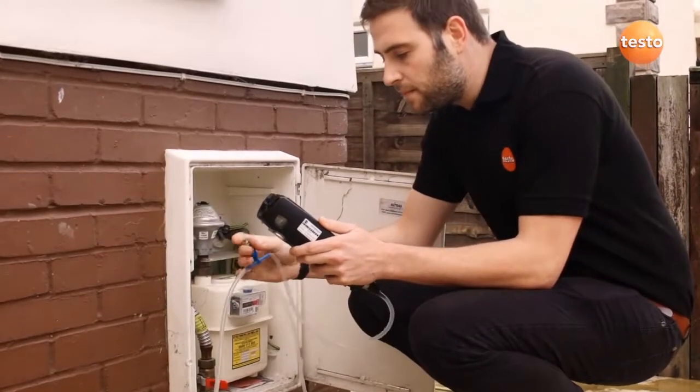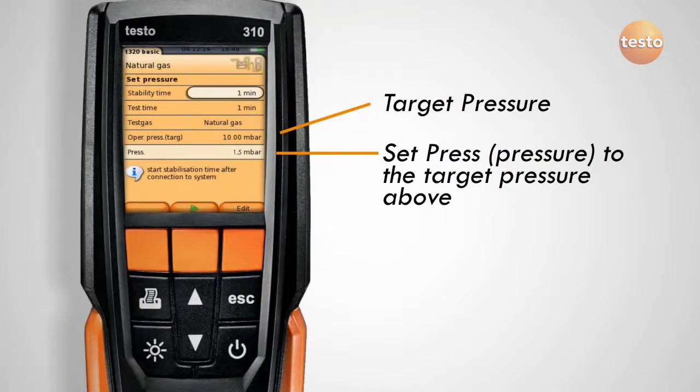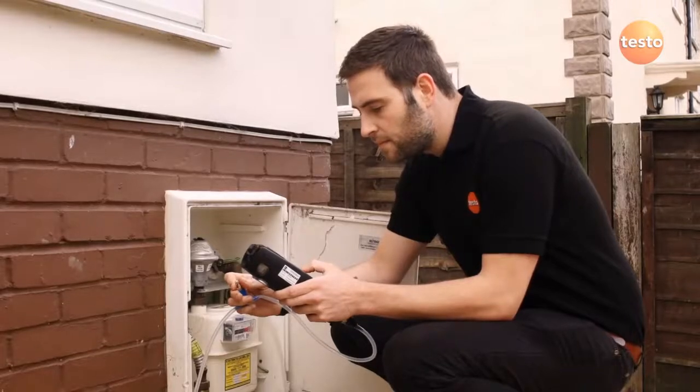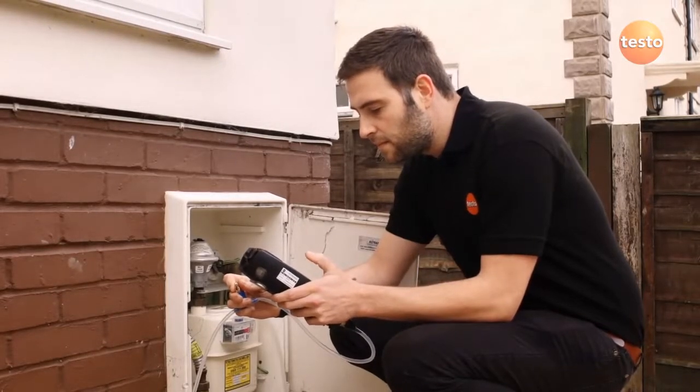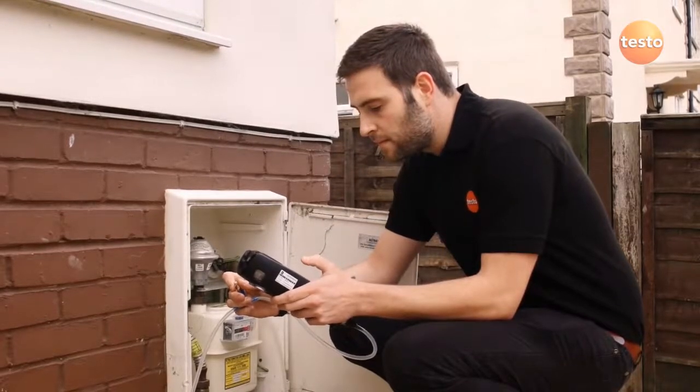Use the blue gas relief valve to reduce the pressure in the system to the target pressure shown on the analyzer. The pressure reading on the bottom line needs to be set to the target pressure shown above, in this case 10 millibars. With the pressure set to 10 millibars, start the stabilization time. If the pressure varies during this period, then reset and start again.